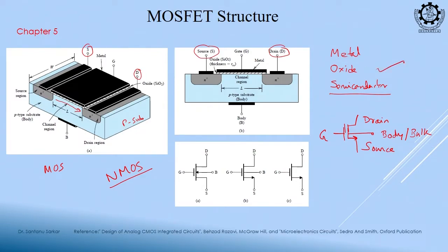So, first was our semiconductor substrate, then source and drain, and between source and drain an oxide will be grown. At a certain temperature oxygen will flow and this oxide region will be formed. So, these are the step by step fabrication procedures.